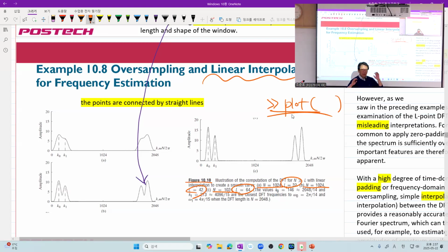So I emphasized a lot, but there are a few choices in our parameter setting. The first thing, of course, is the sampling rate and the related anti-aliasing filter's shape. Got it? So the sampling rate determines a lot. Then the length of the window function, assuming it's of finite duration.